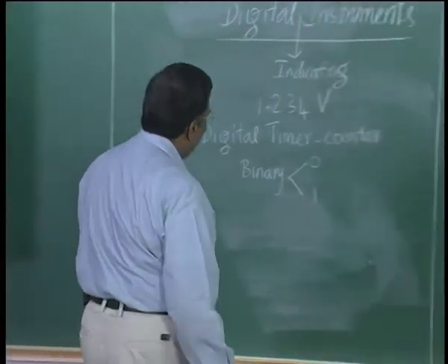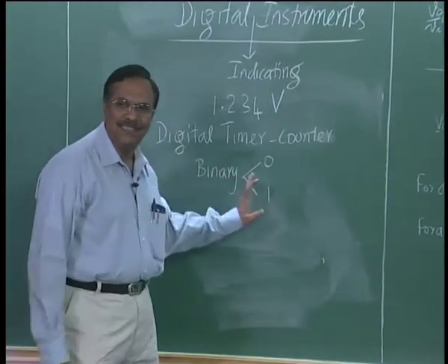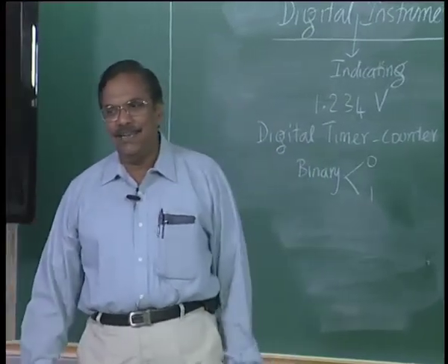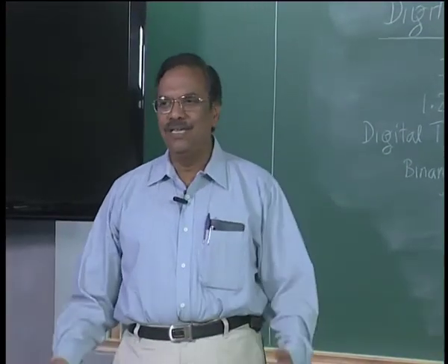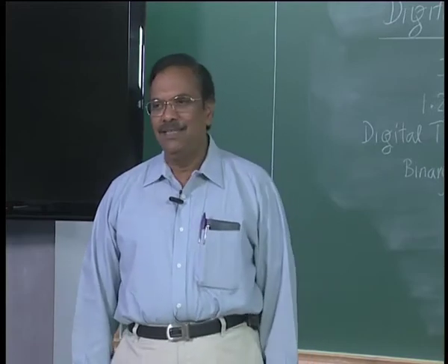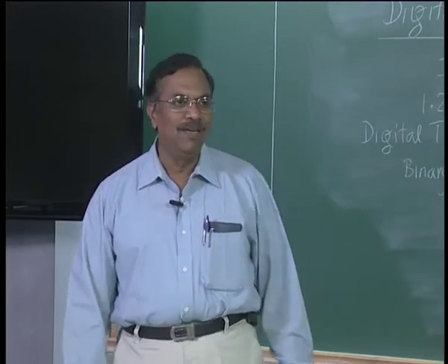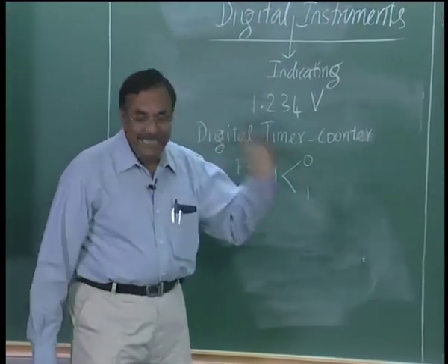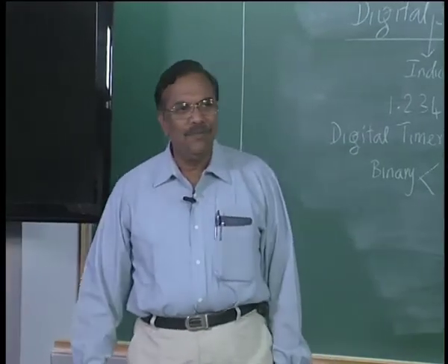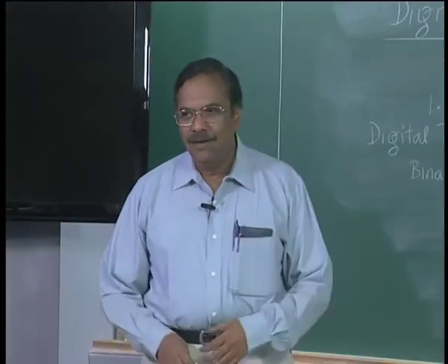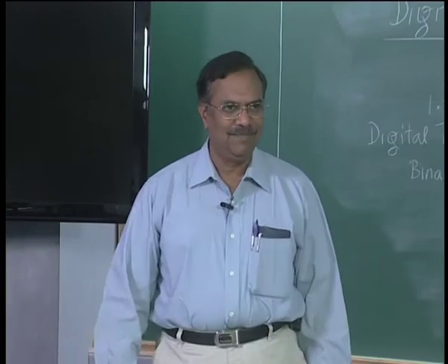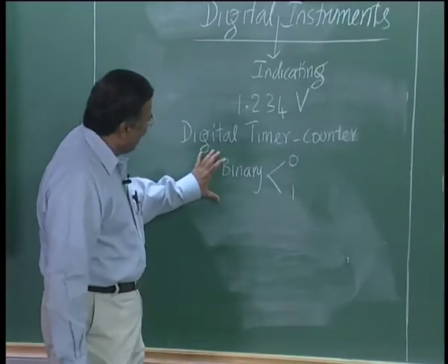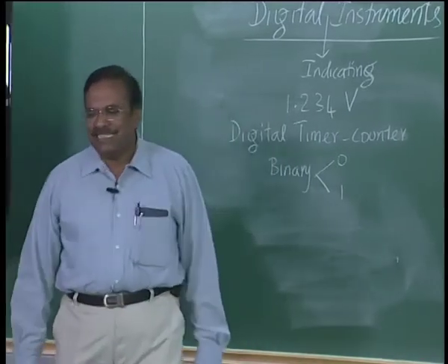We all know in transistor logic, 0 is any voltage between 0 volts and 0.8 volts, and 1 is any voltage above 2.4 volts but below 5 volts. That kind of tolerance made the binary system the system for machine operation, machine computing.